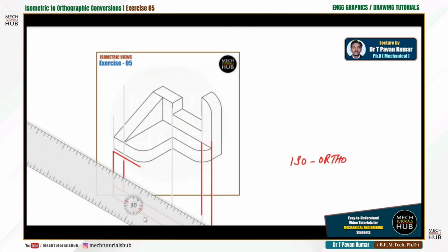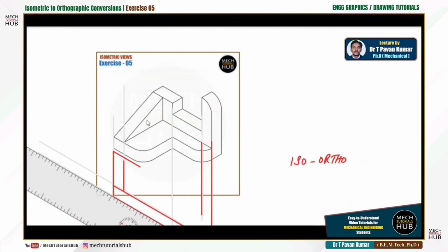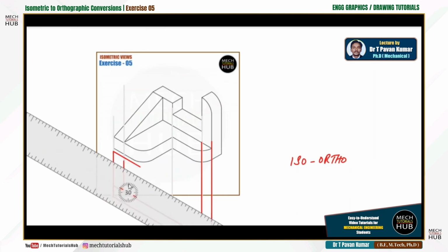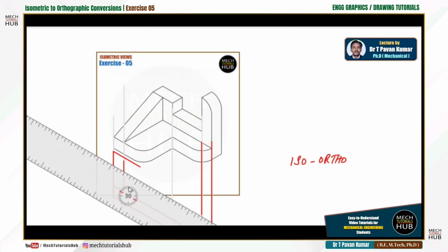Alright, have a look. There is a height from the front visible, and there is one more line extended up to 10 mm. So this needs to be extended to the top. That is fine. After this, it is dropping down up to 10 more mm. This dropping line I'm talking about, this vertical of 10 mm. If this is 10 mm, this is also 10 mm. After dropping 10, again we need to take it. Let me drop it by 10 and draw a straight line till the next line.